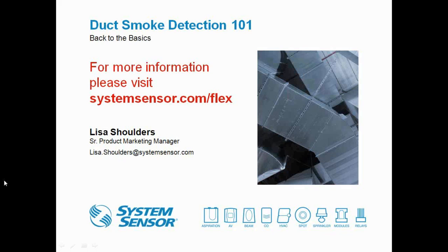Next question deals with sampling tubes, and they're wanting some clarification. They're under the impression that they should span the entire length of the duct width. So they're asking to please clarify if the sampling tube is required to span that entire width. Okay. No, it is not required to span the entire width.